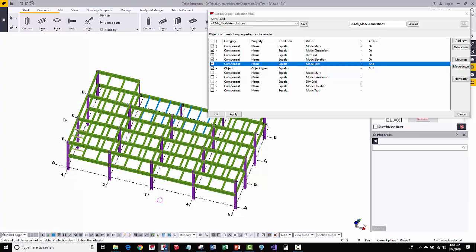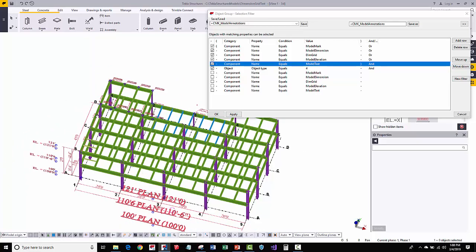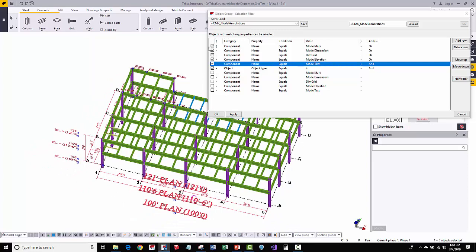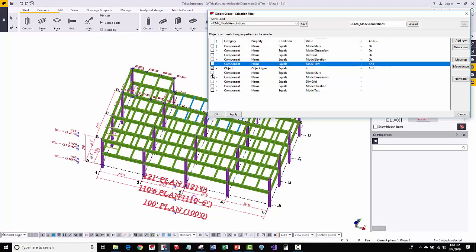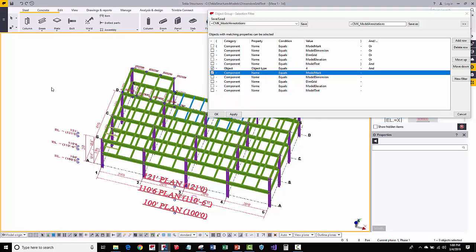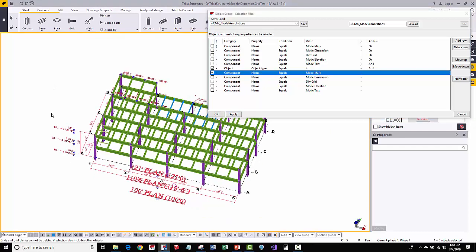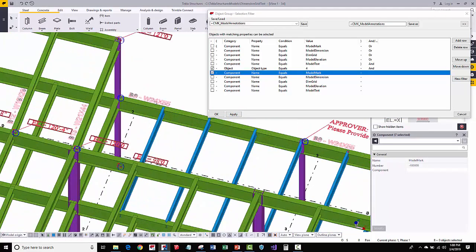Now we don't want to do that because we've done a lot of work here. I simply want to update everything, so all you have to do is use these other filters. Instead of doing all these up on the top, you uncheck these, and then one at a time, you'll have the object type 4 selected, then you'll have model marks selected here, and you'll press apply. Then when you do a Control A, that'll find all the model marks in the model and filter only those out.